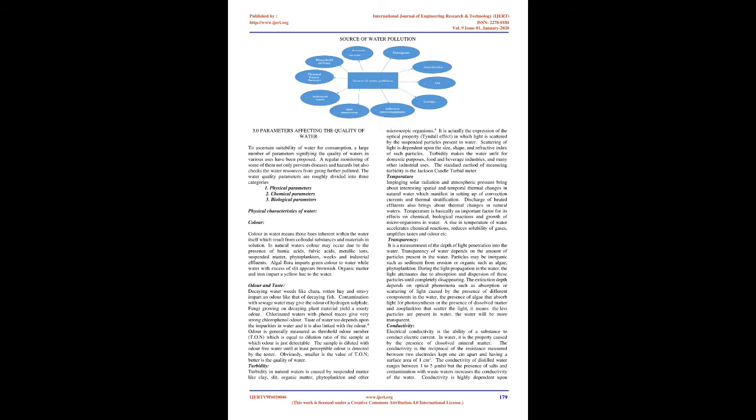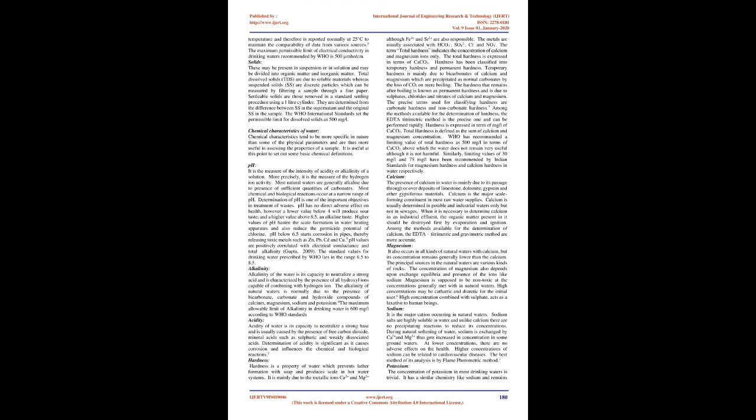pH. It is the measure of the intensity of acidity or alkalinity of a solution. More precisely, it is the measure of the hydrogen ion activity. Most natural waters are generally alkaline due to the presence of sufficient quantities of carbonates. Most chemical and biological reactions occur at a narrow range of pH. Determination of pH is one of the important objectives in treatment of wastes.